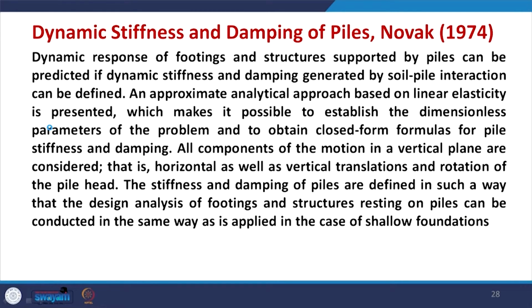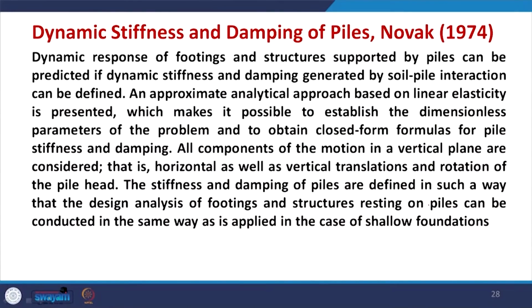So, stiffness and damping, all components of the motion in a vertical plane are considered, that is horizontal as well as vertical translation, rotation of the pile head is considered. So, in this case coupling has been considered, it is not like later on. Initially they have done separately for vertical mode and the horizontal mode of vibration, and then later on rotation has been also considered. The stiffness and damping of piles are defined in such a way that the design analysis of footings and structures resting on piles can be conducted in the same way as applied in the case of shallow foundations.